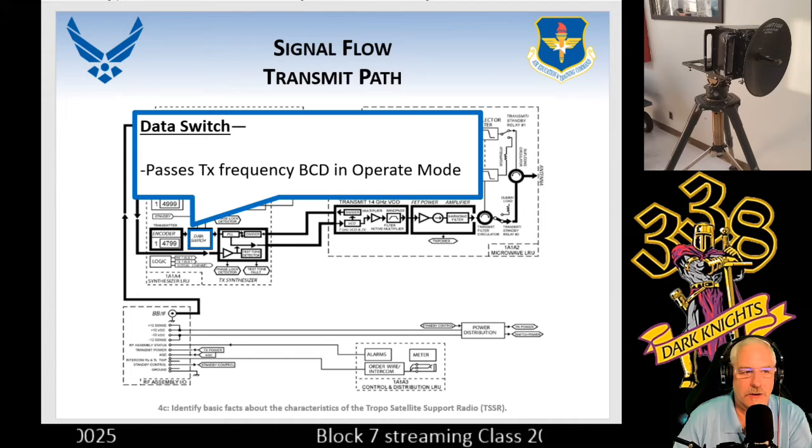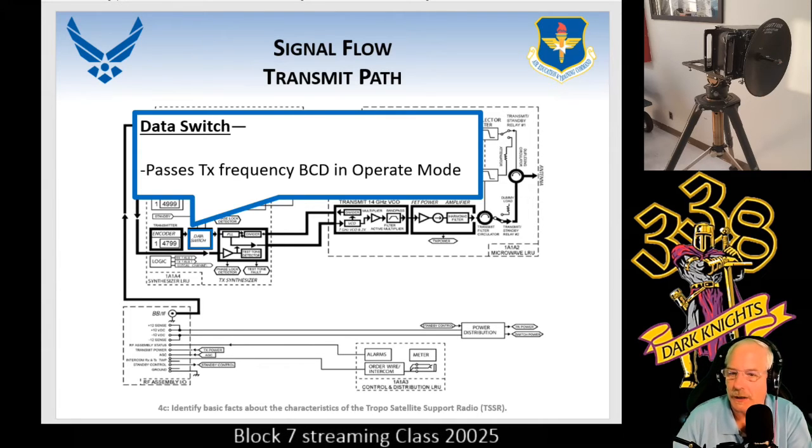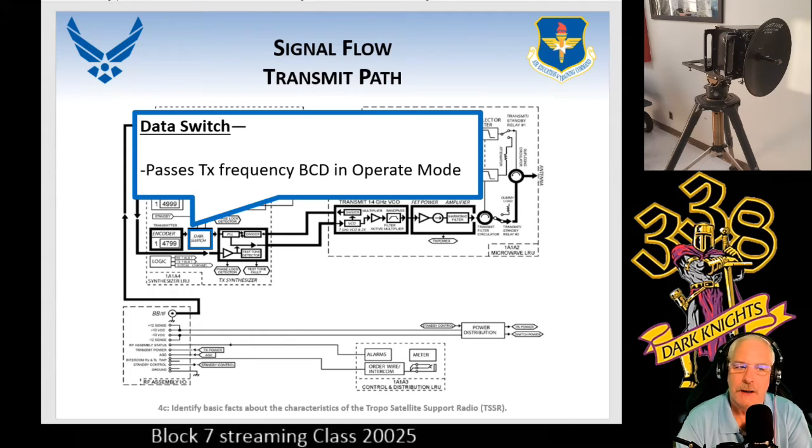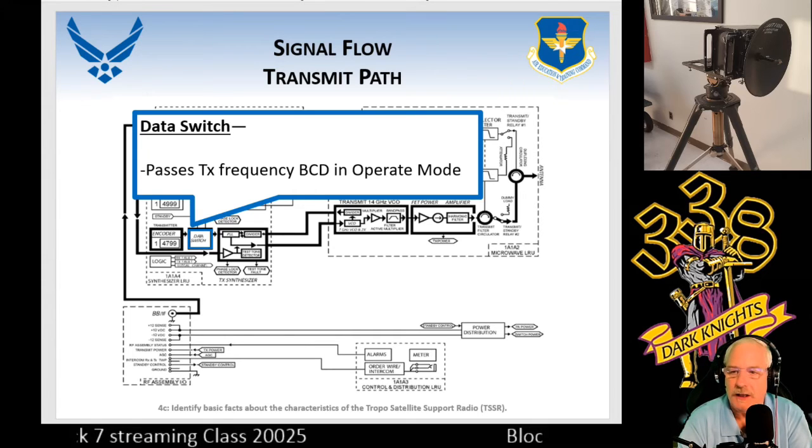The divider is going to come back down back into the phase lock loop box and hit another divider, and then it's going to hit the PLL. Now, the way this works is when we bring our baseband on the same signal as a phase lock loop, it's going to be separate. Why? Because it's a voltage that the phase lock loop is sensing to produce, to give to the VCO to tell it what to do.